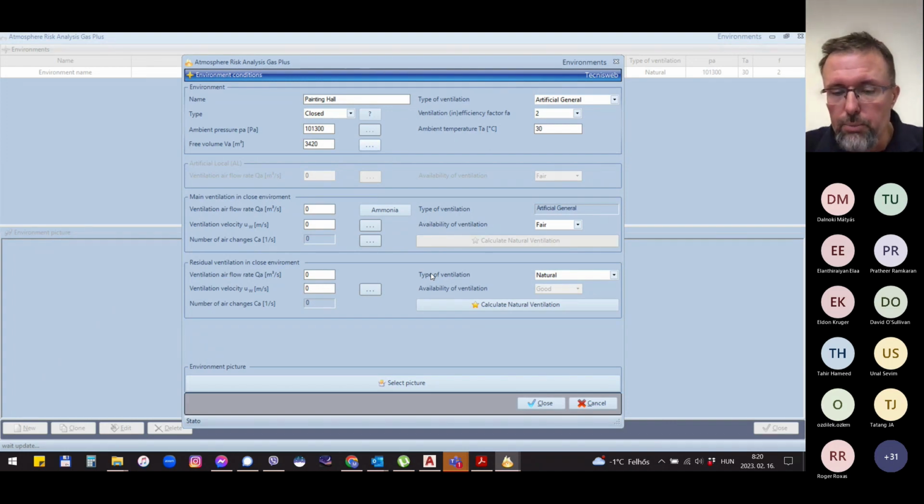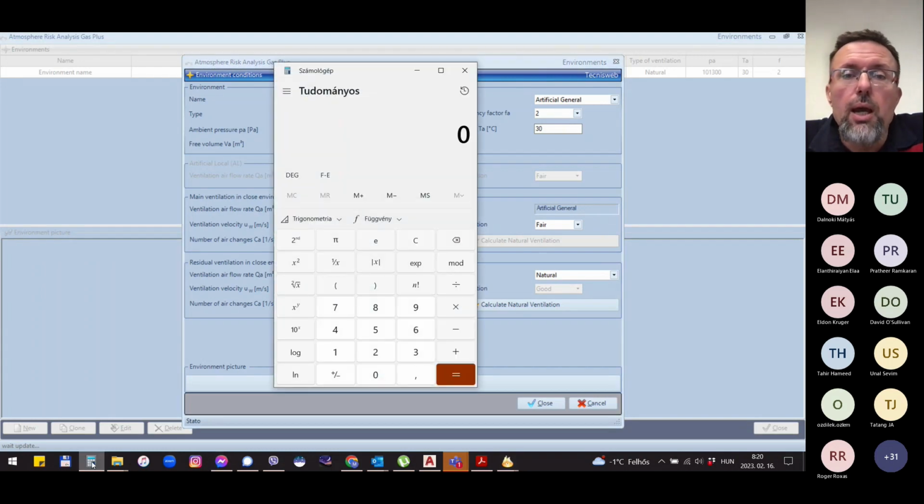And this information, either you get it with a site visit, like a brainstorming or kickoff meeting, or you get it per the user requirement specification. So that's very important. And again, hazardous area classification is part of design. So it requires very detailed and precise cooperation between the engineer who does the classification and the site people as well.